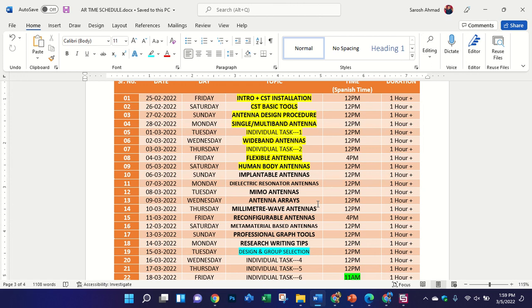And connecting the ground planes, because in MIMO antennas, if you use a common ground plane, then you will not have very good results. That's why people do not like to use a common ground plane. So you need to apply a new technique to connect the ground planes, and you achieve better results.